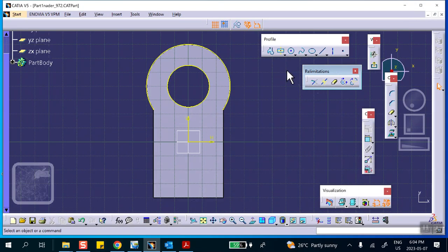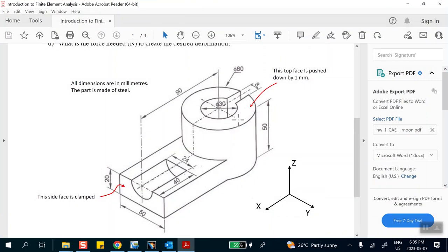So there are different ways of closing that. For example, I can go and say, what is that circle arc? Center and arc, yeah, arc. So the center is right there. Arc goes from here to here. And notice that there is a cutout at this end. So might as well do the cutout here. 8 millimeters wide.